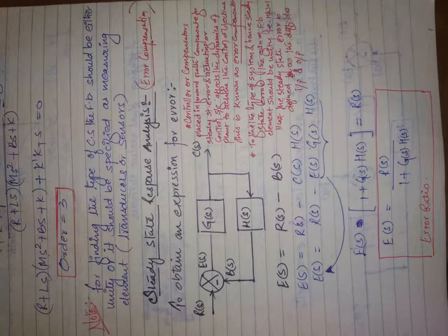I will write this in mathematical terms. As time t tends to infinity is expressed as limit. I write limit as LT, t tends to infinity. Error E of t in this example is how many units? 2 units. Mathematically, this is the expression. At steady state, you are observing this 2 units, which is defined as the magnitude of steady state error and is represented as ESS.